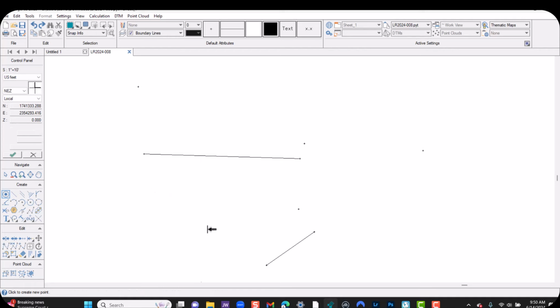Or let's say I wanted 4 points on that line. I'm going to hold down the 4 key, and here we're going to slide across. There's point 1, point 2, point 3, and then of course point 4. So I can put points on that line equal distance apart, 2, 4, 6, as many as I want. Pythagoras will calculate that and show me the location of those points.